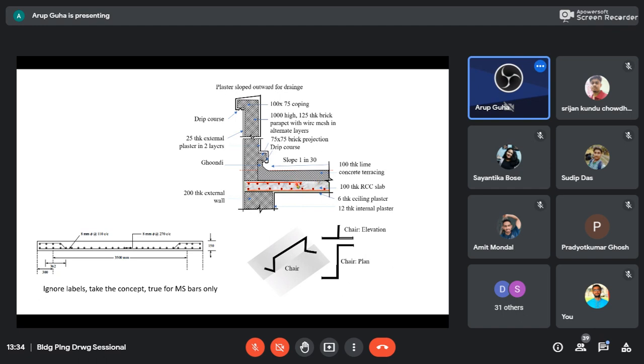If that weakness comes to the reinforcement, it will rust, and rust has a larger volume than the initial diameter of the steel, so it will create a bursting force and the slab will start cracking. Simple mechanics. OK, so let's move on.